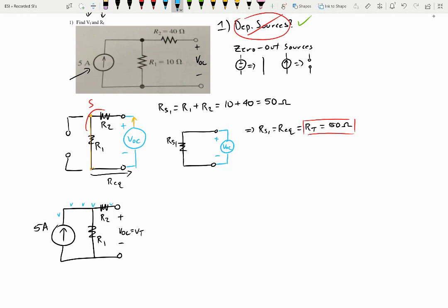So there's voltage there. There's voltage there. So this point and that point have the same voltage. Same deal down here. So voltage here, voltage there, voltage there. So those 2 points have the same voltage. So if we know this point has the same voltage as that, and this point is the same voltage as that, if we can find the voltage drop from the top of R1 to the bottom of R1, okay, cool. Then we can find this.